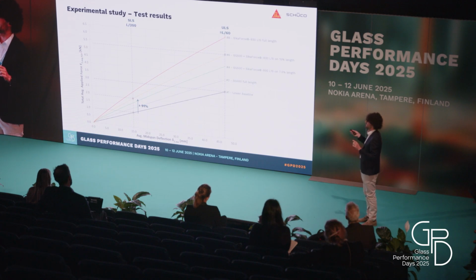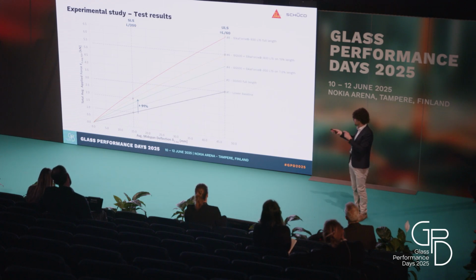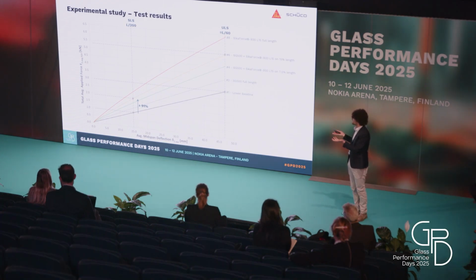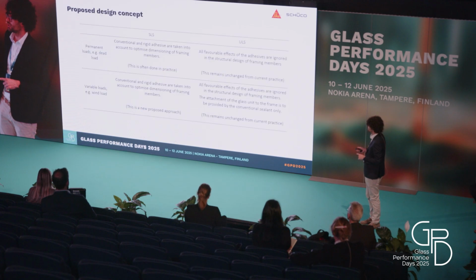And in the best case scenario, with this dual sealant system, combination series number 6, at the deflection of 15 millimeters, so for the serviceability limit, we can achieve an increase on the force applied of 91% to achieve the same deflection at midspan with the different configuration. It's a huge increase of force.